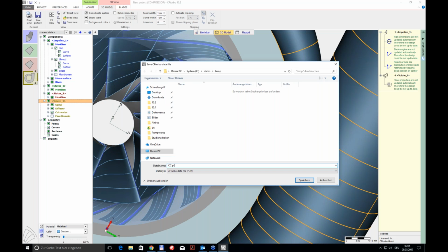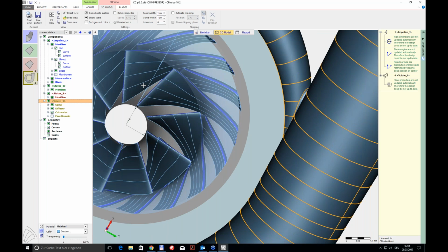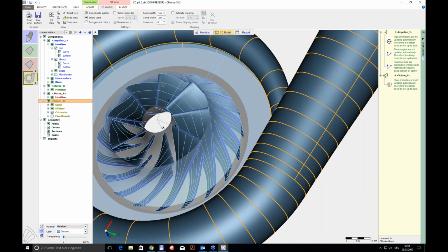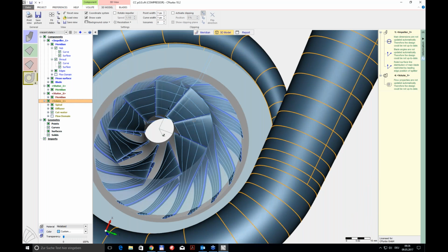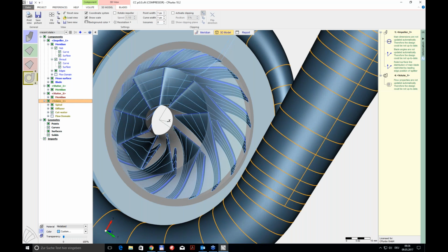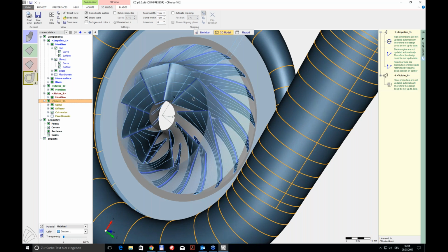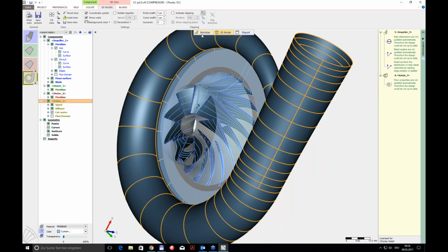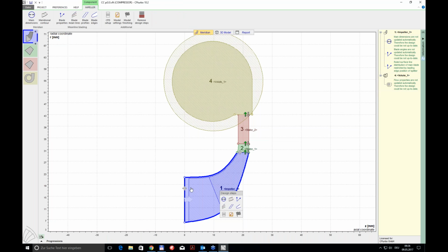I want to change this thing. It's a centrifugal compressor with a certain pressure ratio. That's why I call it like that. And because that was based on 1D design theory together with some empirical knowledge, of course it has to be validated. And to this end, one should probably introduce another stator right at the inlet of the stage.